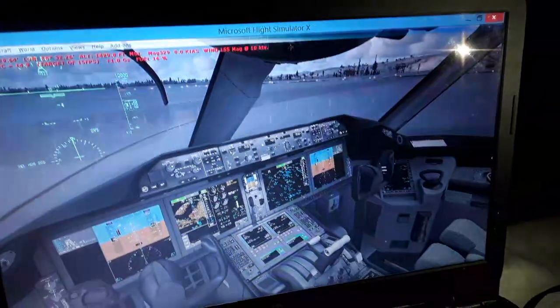occurs. We're gonna select the runway for takeoff in this airport, the LSZH, Zurich International Airport in Switzerland. We're gonna select the runway 14, both for takeoff and for landing. The runway length, the runway slope, the wind direction and speed, the barometric pressure, the density of the air, and also other data, the temperature of the air, whether the runway is dry or icy or wet, and it's gonna give us also the flaps we're gonna use for takeoff. We're gonna use 15 degrees for flap.